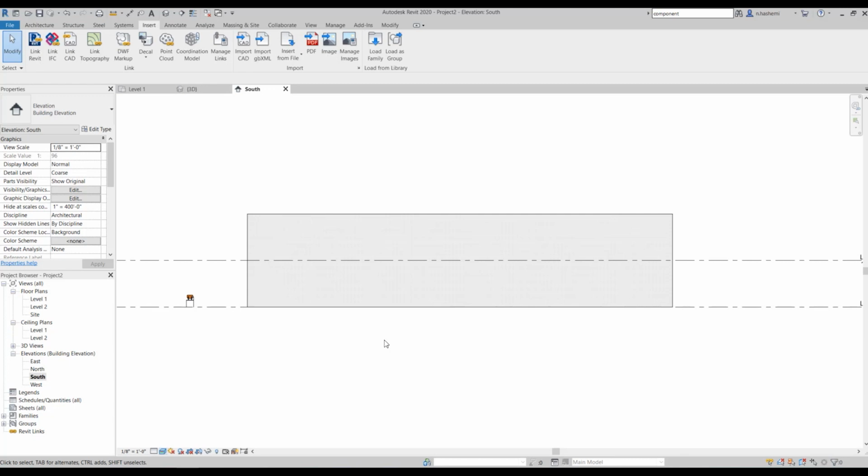Well, the way we change a material by face is actually by using the paint tool. There is one important thing here you should pay attention to, and make sure to just write it down. When you change a material by face, for example, if I paint this raw brick, it wouldn't have information stored inside of it. It would just look like brick.